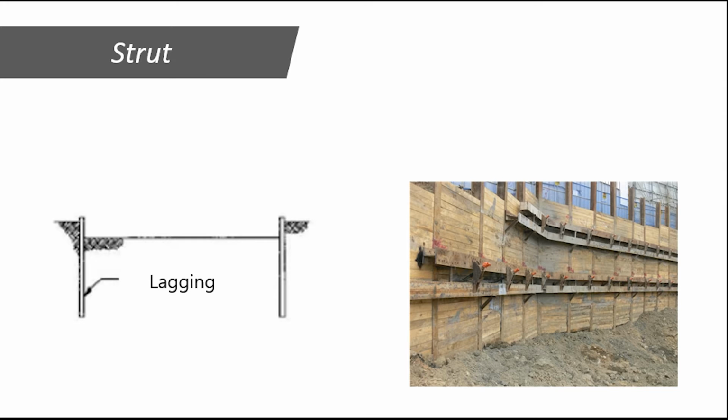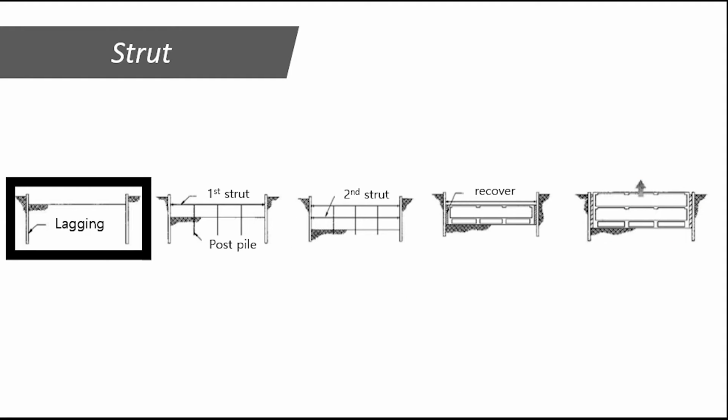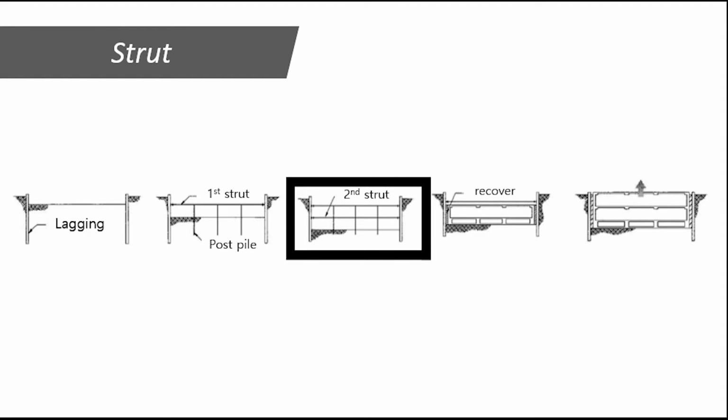Next, install the post pile, install the first strut, and dig the second stage. Then install the second-stage strut and do the third excavation.